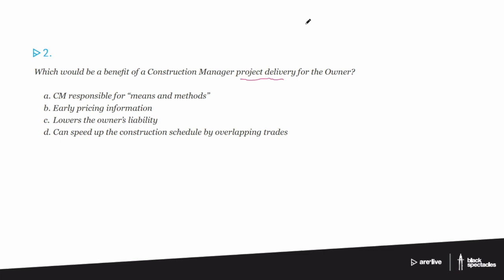Another project delivery method might be design-build, where instead of having that whole separated process, you, as the owner, hire one entity. It might be two different companies, might be one company, but it acts in terms of the relationship to the owner as one entity, and it has both the designers and the builders all put together in that one entity. So it clearly has a very different sort of delivery of the project. It has different contracts, different relationships, and all those aspects are quite different. So there are a number of different ways that you can deliver a project. The construction manager concept is another one.